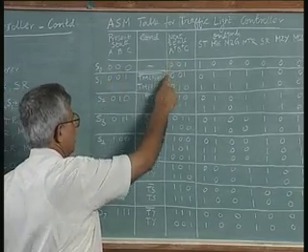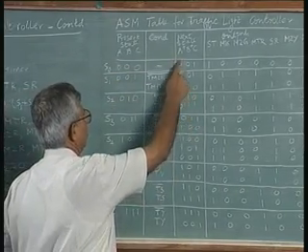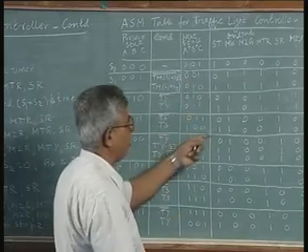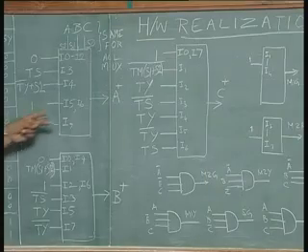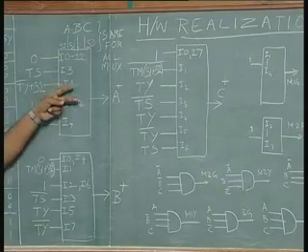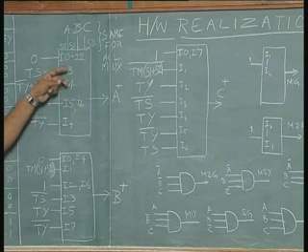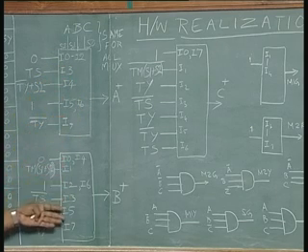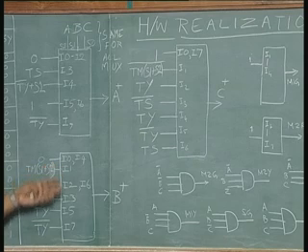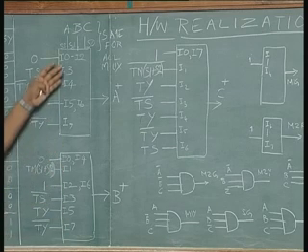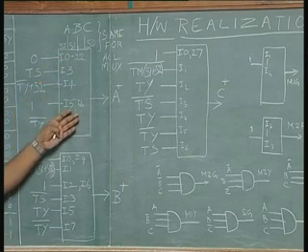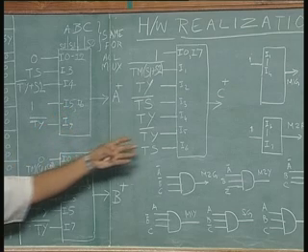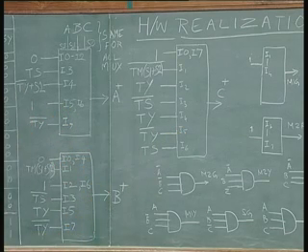For all these states, the next state variable of A is 0. So all of them have been combined again to reduce the drawing. Like that you can write the input conditions for each of these inputs I0 to I7 for each of the multiplexers A, B and C, and then the outputs can also be given by a multiplexer.